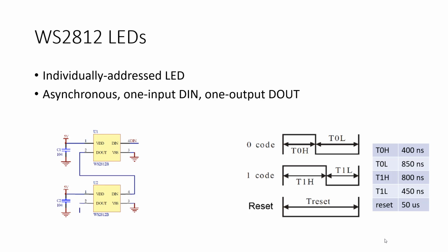not seconds. It doesn't know seconds, it knows clock cycles. But we're at 80 megahertz, right? So you basically say how many 80 megahertz clocks you want it to be high and how many you want it to be low, right? And that goes into one entry in the script, or in the RMT RAM. When you put that in, you're basically just telling it how to transmit one bit.